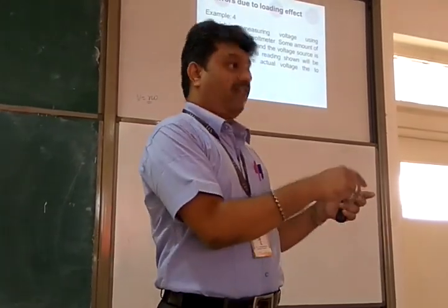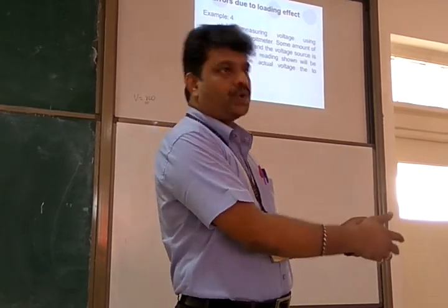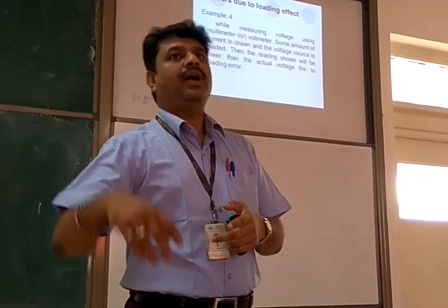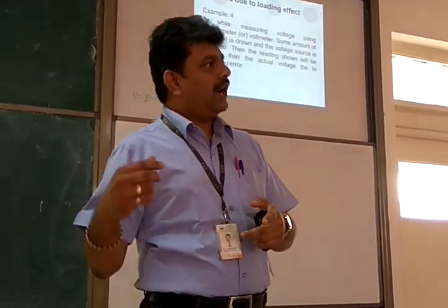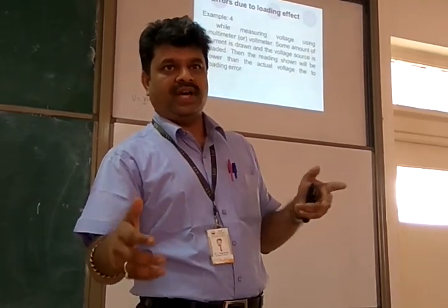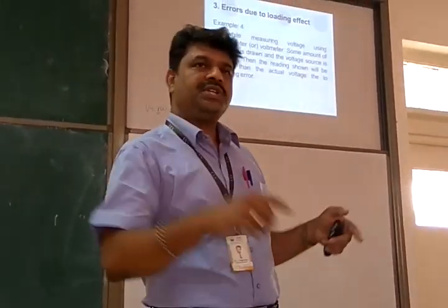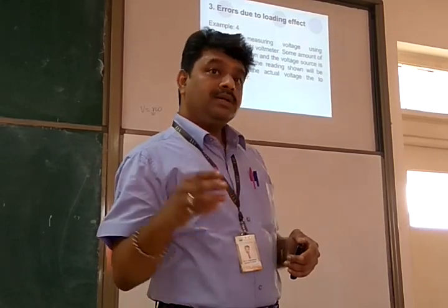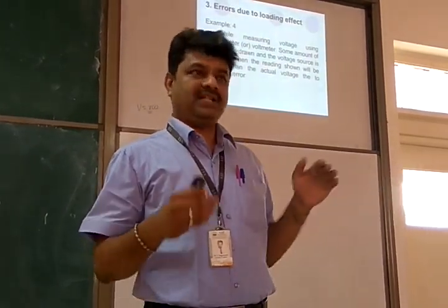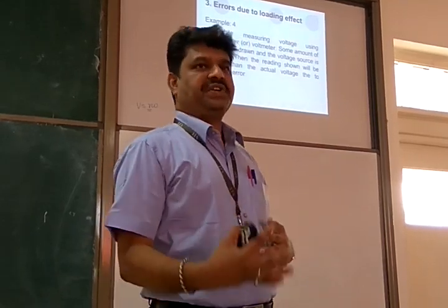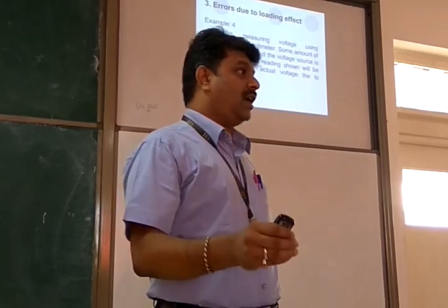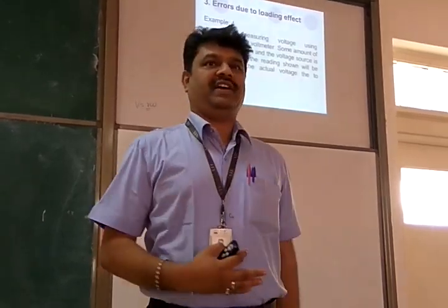For the purpose of measurement, actual voltage is taken, passed through a resistor, voltage drop is computed, and from the voltage drop, the multimeter understands what is the voltage at the source, and it displays that. Some amount of drop is there. The voltage is no more the actual voltage. It is disturbed, no more the same voltage. The amount of disturbance that it causes is actually a loading.